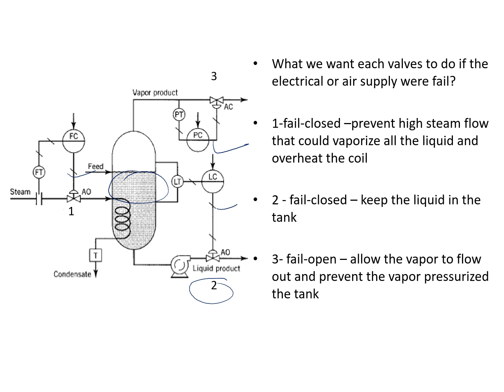For the second type, which is the level control system, if the energy supply is cut off, logically we don't want all the mixture of fluid inside the tank to leave the tank. If the liquid inside the tank leaves without any restriction, the level of the tank will decrease, so the tank will dry.